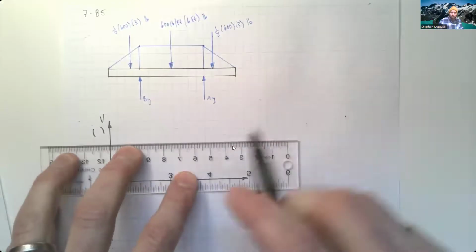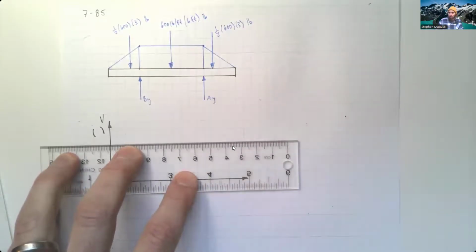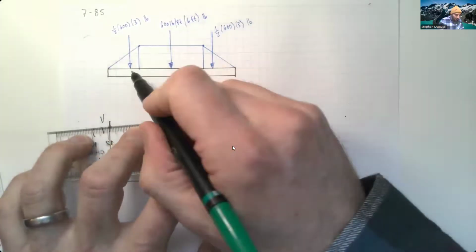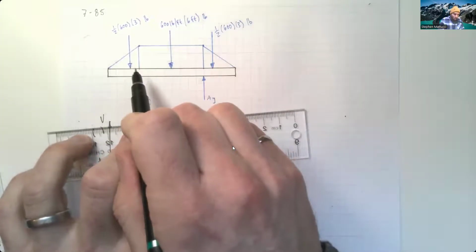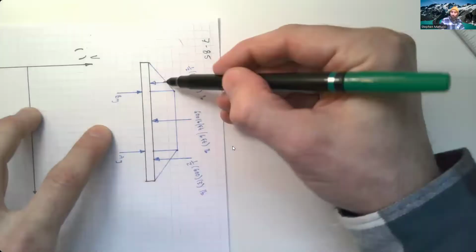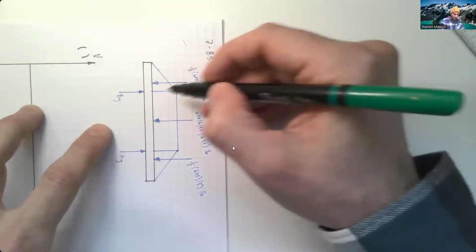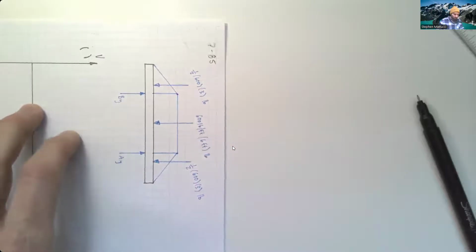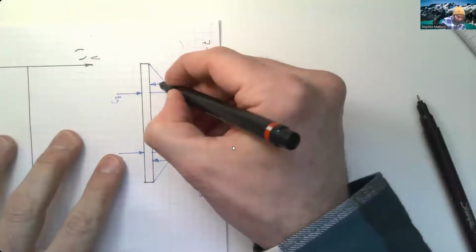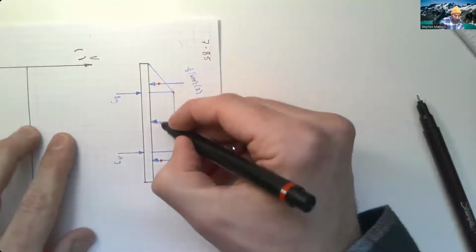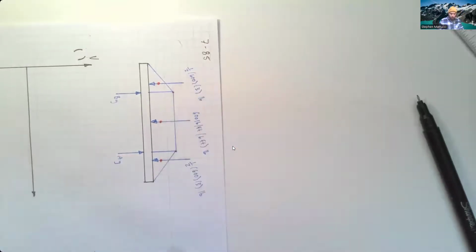So now it's also going to be really important to determine where these resultant forces are acting. So we know that our centroid is going to be 1/3 from the base. And so if we switch our triangle like this, what I'm talking about here is if this is our triangle, 1/3 of the way up the height is where that force is going to act there. I'll just put a little red dot here. So the red dot on each of these is just showing where that centroid location is.